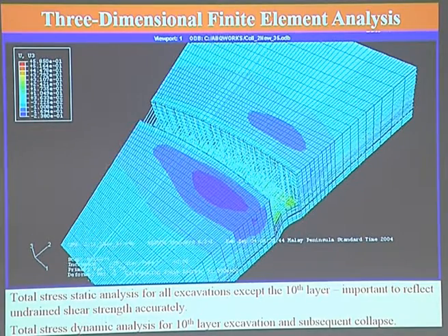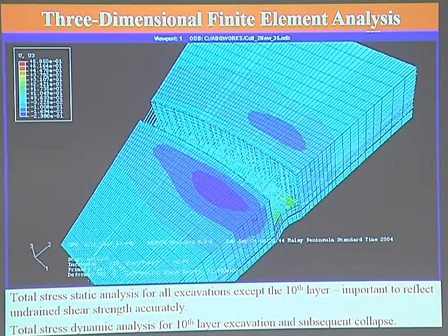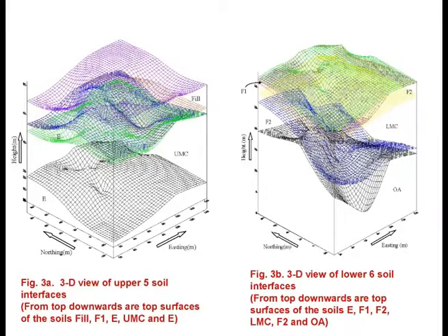And because we were doing dynamics for part of the way, we felt that we can't do an effective stress analysis. Abaqus doesn't allow us to mix effective stress with dynamic analysis. So we can only do total stress. So anyway, that's what we did.